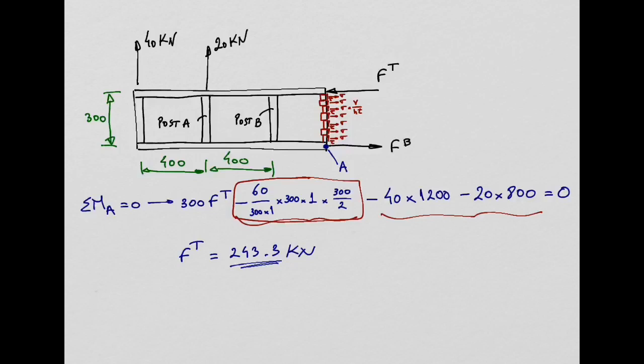Yeah? So it means, due to the development of the buckling on the web, we are overloading the flange with more force, yeah? So we need to make sure the flange is able to carry that load without failing, okay? That's why we need to calculate the force in the flange.